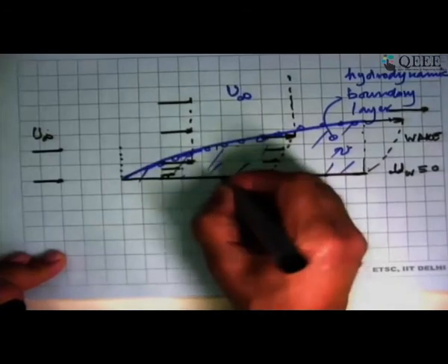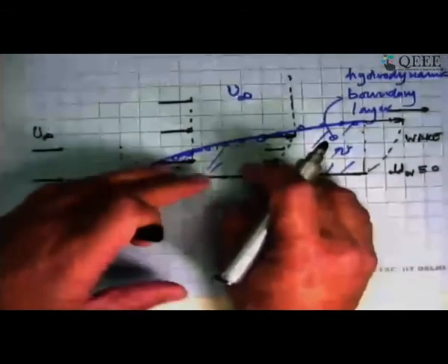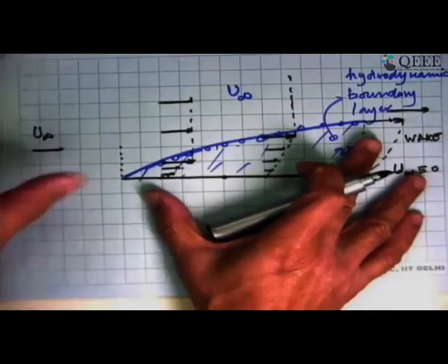We cannot just solve the equation for a small region and say this is the skin friction coefficient at this point. Not done. Every fluid element has experienced some way or the other what is happening here. And the final solution, whether analytical or a computer solution, we have to take a domain which includes the boundary layer and a lot of fluid on all sides of it. Only then our answer is going to be correct.